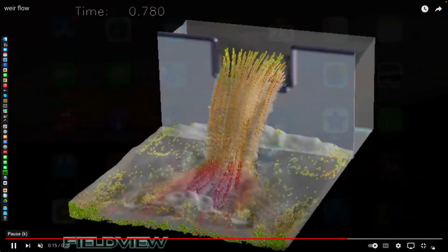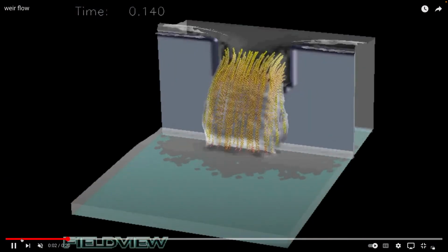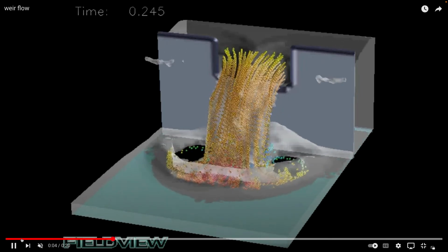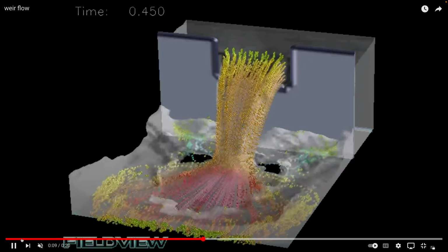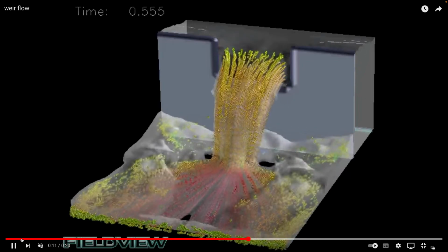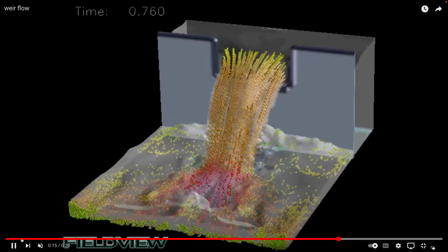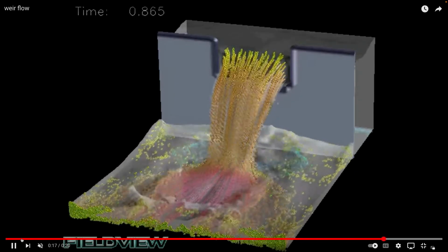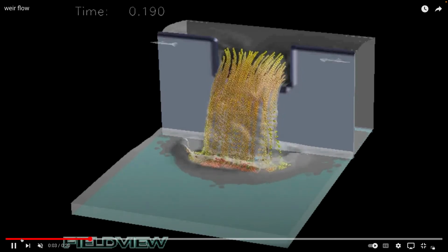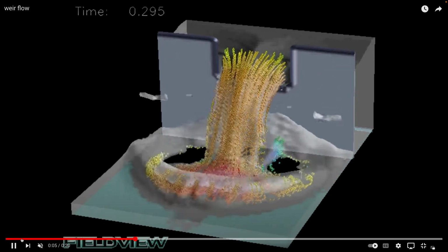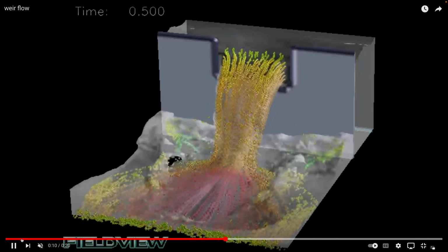And so measuring flow rates is not so easy. You could imagine discharging this into a bucket, seeing how long it takes for the bucket of a known volume to fill, but that's typically not very convenient for us. And so one way to do it is to use Bernoulli, and instead of measuring a flow rate as an accumulating volume in a bucket, to measure a pressure difference between 2 points, and to try and use that pressure difference to be able to infer what the flow rate is.